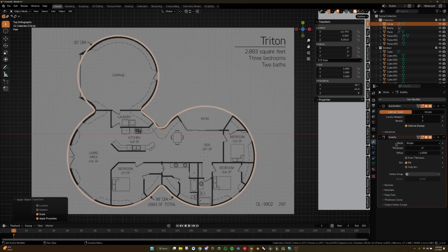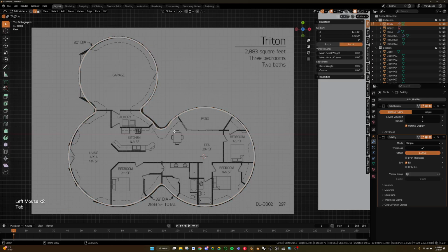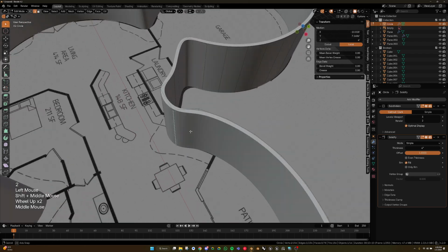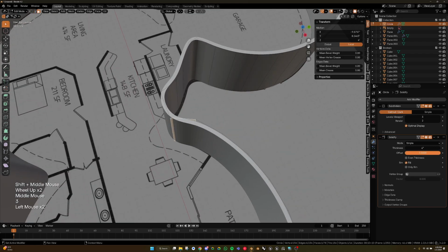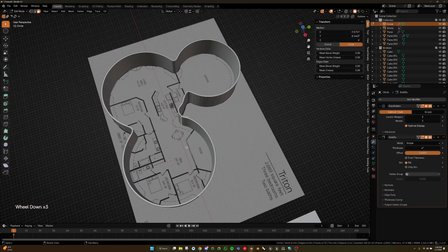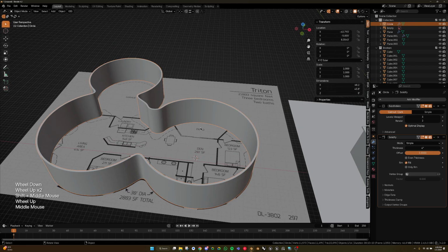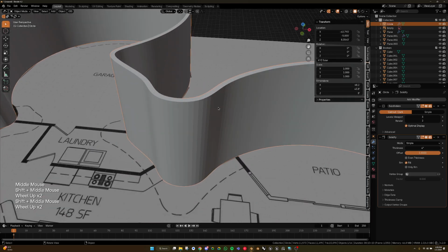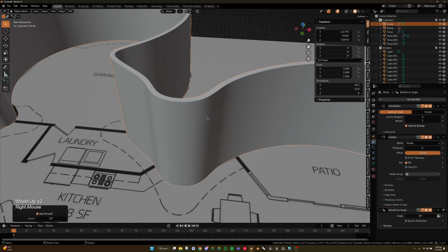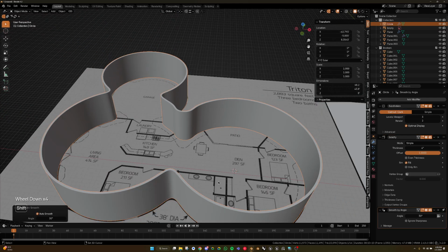Interesting. Okay, I guess it's 4 inches. You could also adjust the offset, so where the walls are in relation to this face, right? And then you could just kind of place it. I'm just going to do that. It's close enough. If you don't want to see these edges, just right click and do Shade Auto Smooth, and it should make it nice and smooth for you.